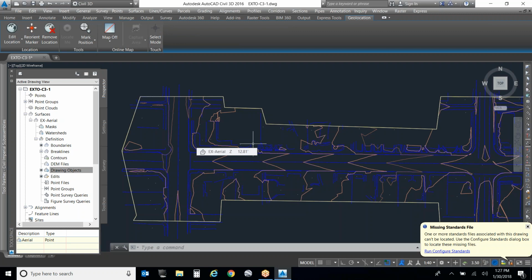All right? I've seen people use aerial survey and take the accuracy of the earthwork down to a 100th of a cubic yard. You're lucky if it's 50 cubic yards or 100 cubic yards. Okay? So be aware of the accuracy. Any questions or comments? Steven?